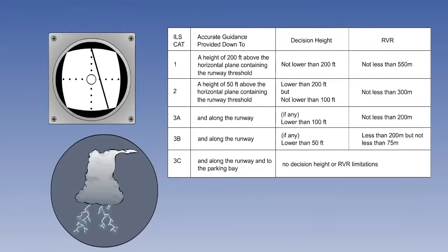In this lesson, we have seen how to interpret the CDI and the HSI, when to fly left and right, up and down. We have seen that there are 3 categories of ILS with different missed approach points. The ILS transmissions are subject to the usual factors that cause inaccuracies. We have done some basic calculations, and we have flown the Oxford ILS.